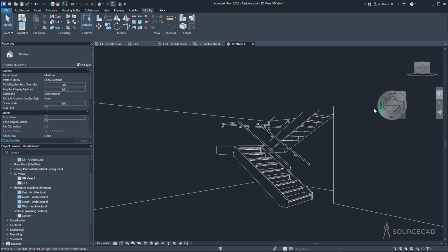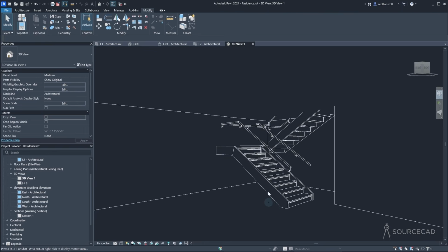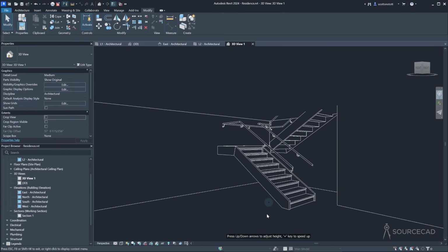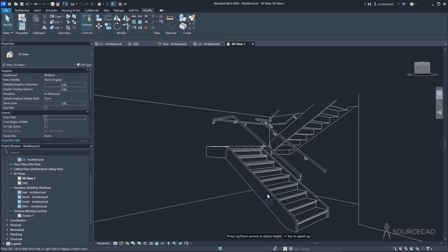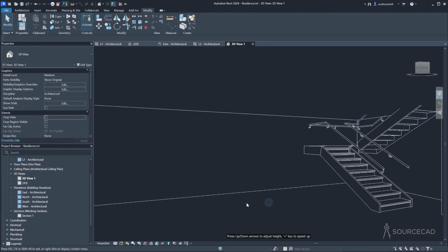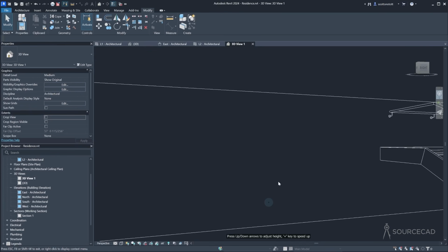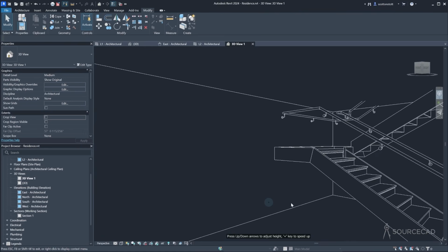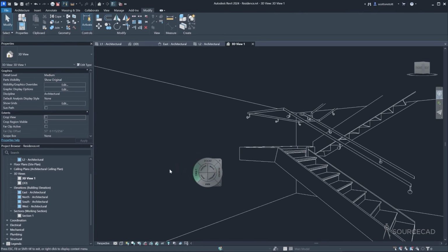Then I'm going to use the steering wheel. And this is how we navigate around an interior. So I can walk by dragging on this, and I can walk around, go left and right, and real subtle motions are what you want to do here. And it's all relative to this dot. So the further away from that I move the mouse, the faster I walk. So I can walk over here and then turn right and position myself so I can see what's happening here a little bit better. And then close that.